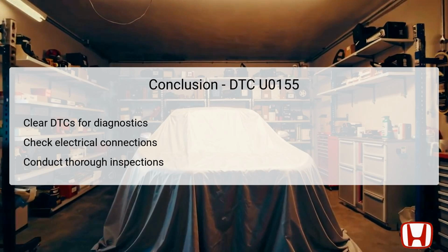Careful inspections of electrical connections, circuits, and components are vital to identify the root causes of communication failure. Each troubleshooting step serves to verify voltage presence, connection integrity, and proper functionality of critical components like the gauge control module. Implementing preventive maintenance will also assist in mitigating future occurrences. By following these steps diligently, technicians can ensure that the dashboard system remains functional, supporting vehicle safety and reliability.